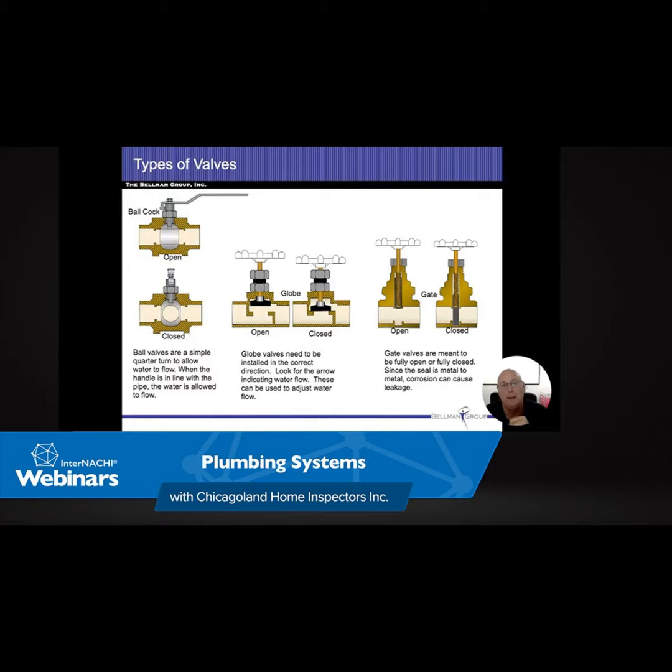So this one we kind of saw before. It's a repeat. Next one is going to be an oil burner coming in there. When we do the heating systems, you are going to be expected to be able to identify if a heating system is an oil burner versus gas versus electric, whatever the different fuels are going to be. Typically the oil burners have a regular pump like this that's going to pump in air pressure. It's going to pressurize the oil itself. It's going to create